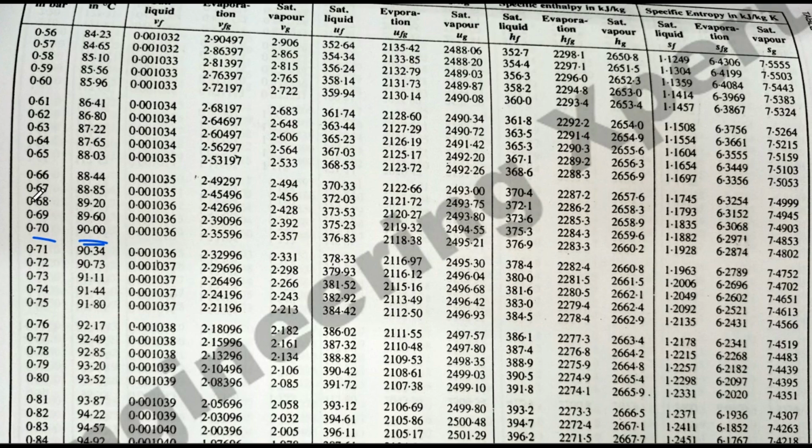So if you get only temperature and pressure as the parameters, then definitely it is outside the dome, because you cannot find the value of x with just temperature and pressure. So it must be the superheated region or subcooled region, and you need to work accordingly. You know how to find enthalpy using Cp for subcooled and superheated, so you need to do it that way.